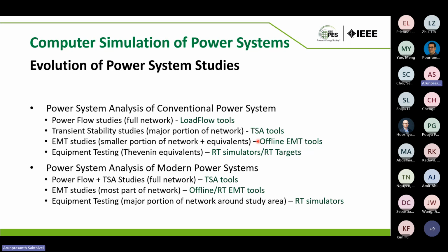But moving towards the modern power system, where we have inverter-based generation and resources everywhere, power flow and TSA studies are done for almost the full network using TSA tools, and EMT studies are done for most of the network using offline or real-time EMT simulation tools.